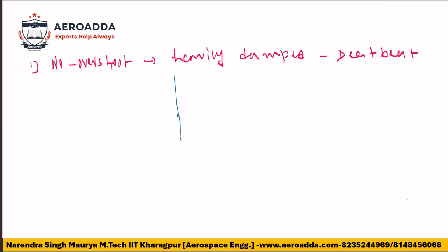So after the disturbance, the aircraft will respond. There will be a time response for the aircraft, but the amplitude will be decreasing like this. Check the graph. Here the Y-axis is displacement, and this is, obviously, time. Correct.